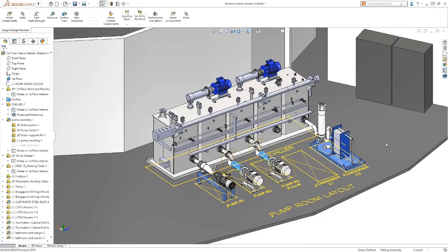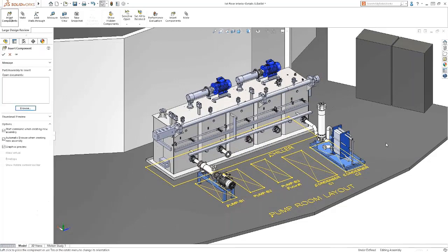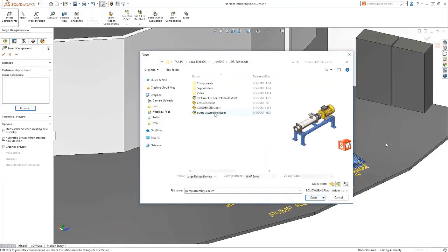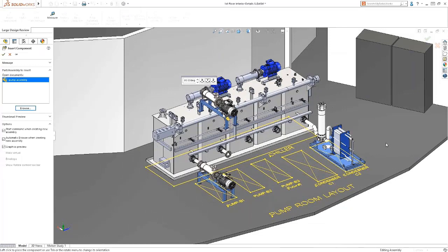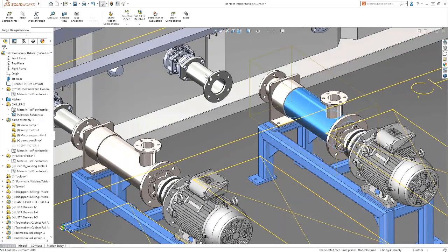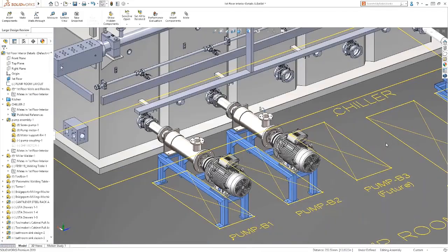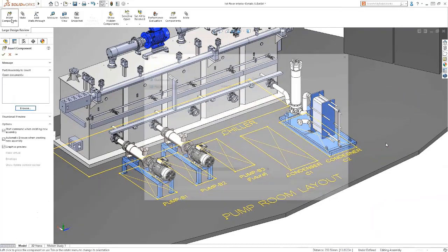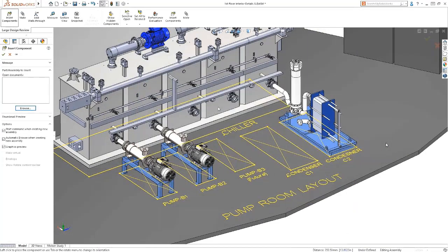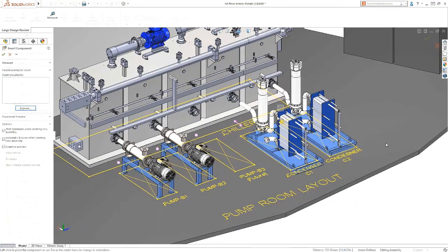If you're looking to delete a few components that may not be needed, this can be done in the new edit mode. New components can be added to your design, just as you would in a fully resolved assembly, and these new items can be placed and mated into their proper positions. Mating is done just like you would in lightweight or resolved mode, including the use of the Quick Mate toolbar. Components that have been prepared to use magnetic mates can be assembled as well and snapped into position, saving a great deal of time when doing large facility layouts.